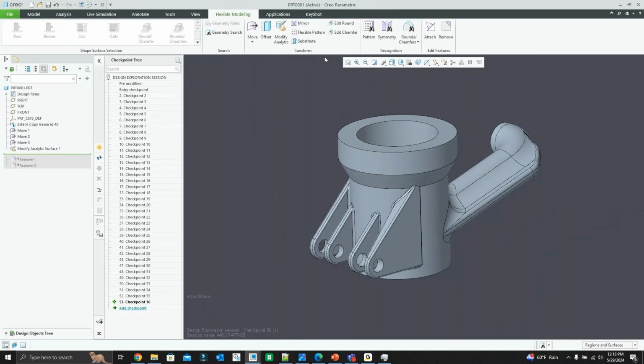My Bambu printer prints at a better accuracy than my Creality printer. Not that Creality doesn't have a better printer, but the model that I have gives me pretty good prints, but the Bambu printer gives me more accurate prints. And then also we have the different filaments that we can use. So if I'm printing in a rubber TPU material, that print result will be different than if I'm printing in PETG or something. In my own experience, when I printed parts going from one filament to the other, I typically have a change there. It doesn't necessarily fit the way that it should. So there is a lot of tweaking that has to happen,